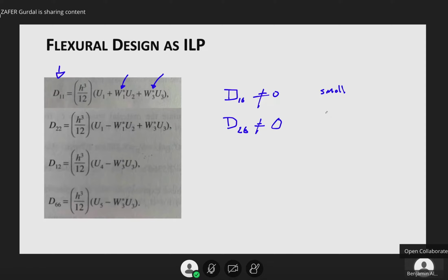If the plies are not lumped together, that is, let's assume that you have a 36 ply laminate made of zeros, plus minus 45s, and 90s. That's 18 layers, half the laminate. So if I look at half the laminate, 18 plies, this is the mid-plane.